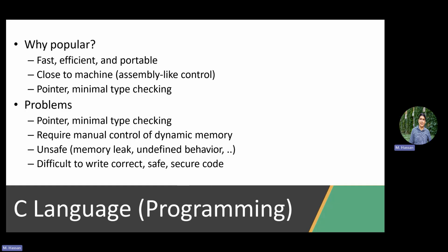So simply, pointers allow you to address a particular address, right? Like I go there and write, I want to access location 0xFF3F, for example, which is the register of the GPIO, I mean, port A, for example, in the controller, right? No other language enables you to do this. So that's a very big advantage. What is the disadvantage? It's very hard to code and also susceptible to human errors, right?